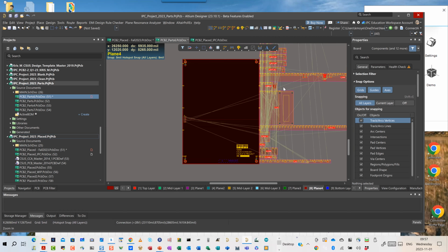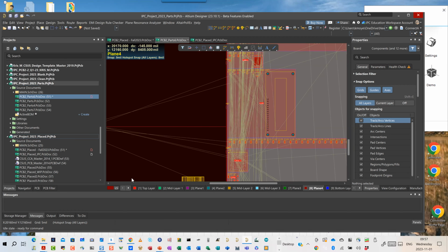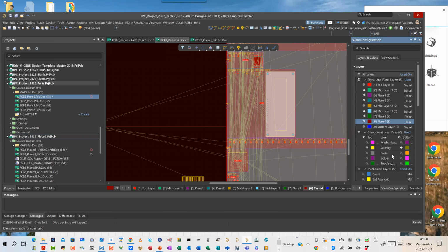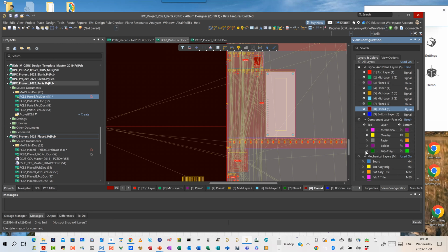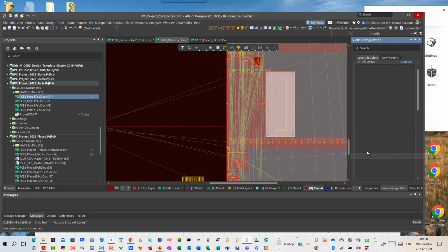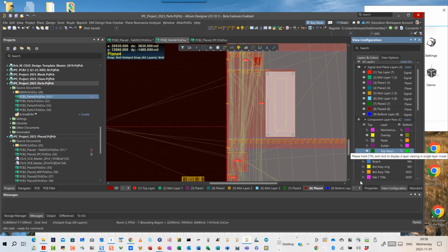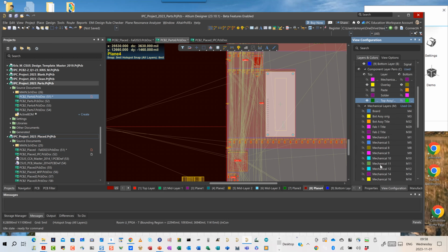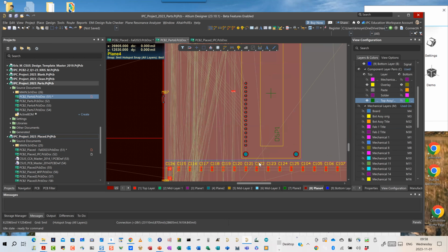One other thing, for those that stayed around, that watched how I built the LCD module right here. Okay, so I'm going to grab the display module right here, and this is where one of my extra layers is going to come in handy. And that's this one down here that I'm calling top assembly right here. So I'm going to turn that layer on. That's my mechanical 15 right here. I want to make sure that I don't also have it down here. Yep, it's that one right there. And hopefully I did that right here. You can at least see the DSP1 right here.